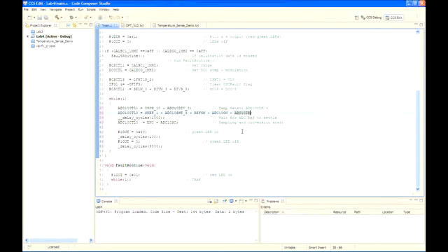The REF ON parameter turns the reference generator on. We're going to have to wait for the reference voltage to settle after this line. ADC10 ON turns the peripheral on, and ADC10IE turns on the ADC10 interrupt. We don't want interrupts in this lab exercise. We haven't covered interrupts yet. So go in there and change that line where it says ADC10 ON, ADC10IE. Go ahead and take ADC10IE out of there.